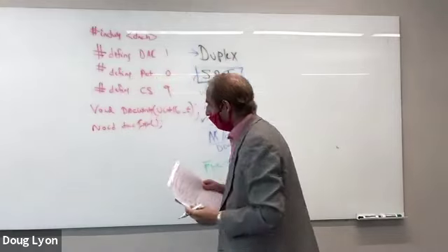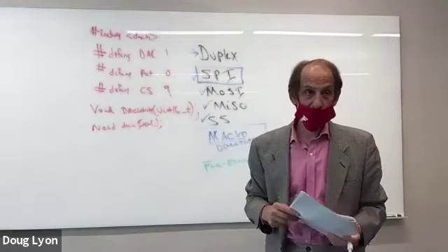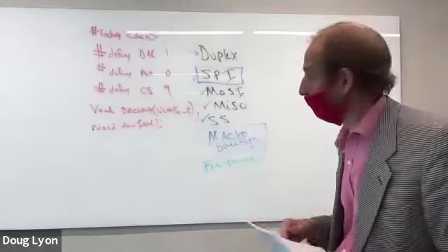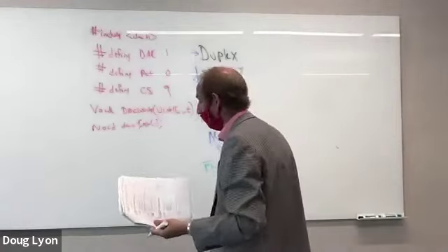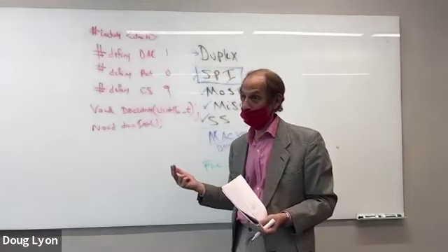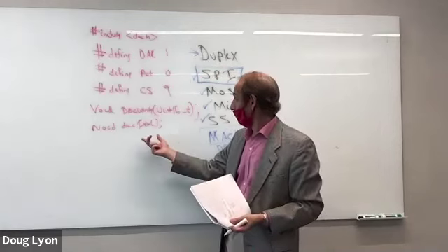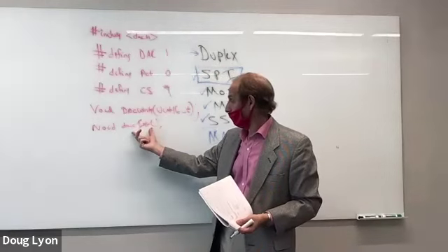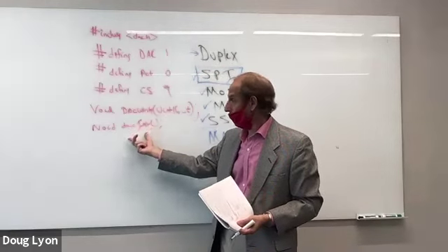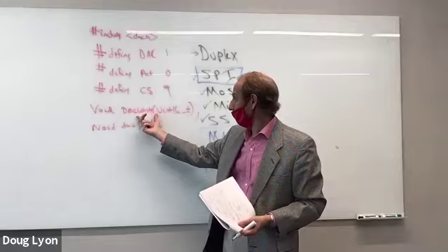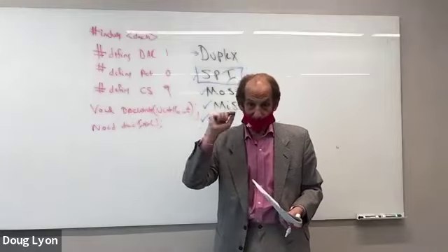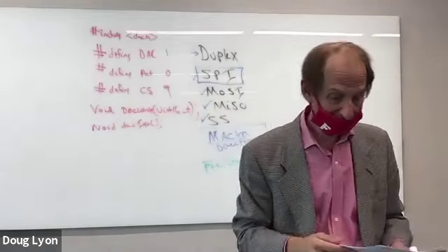And so what you can do once you include a subroutine library like this, and you have to know how to use subroutine libraries. There's just no way around it. If you're going to program microcontrollers, you've got to know how to do this. You're going to have a setup which does a DAC init. That'll initialize the DAC. Then you're going to call DAC write repeatedly, and then you're going to write out data to the DAC on your sound card.